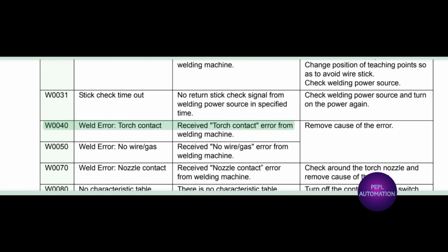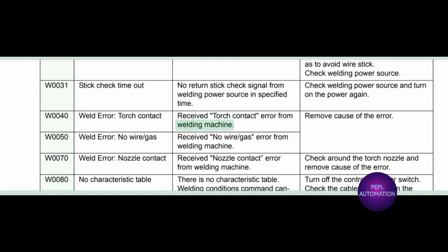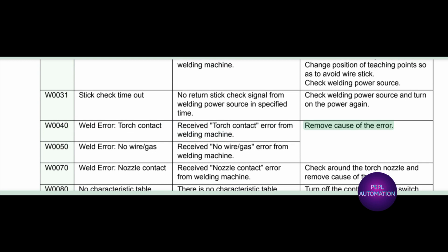W0040 weld error, torch contact received. Torch contact, error from welding machine. Remove cause of the error.